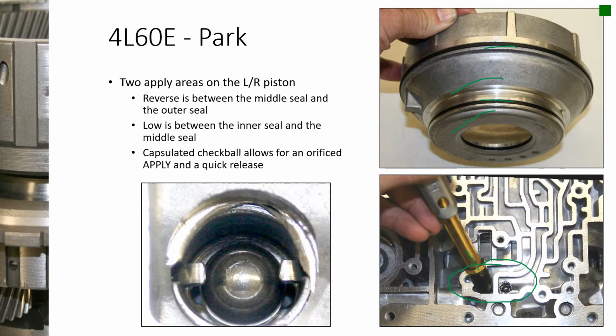I can fit an air nozzle into this one because it's just a hole, but on this side I need to use a plate or a rubber puck or something to go over it, because there's no good way of getting the nozzle to seal off against that check ball. But you definitely want to air check these things just to make sure that the seals are solid. You shouldn't hear any air leaks or anything when you apply air pressure into these.